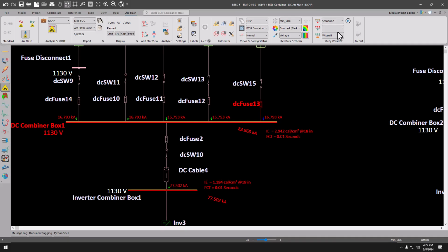And as expected, of course, our fault currents have been reduced. Therefore, our incident energy only came down because we still have enough fault current to trip those fuses in a rather quick amount of time. But in both cases, you're able to see that even though we never formally ran the analysis until right now, the C area curves helped us get a visual confirmation that, based on the protective device connected to each of these different fault locations, our reference curve was able to guide us and let us know that we will be able to attain that target incident energy limit.